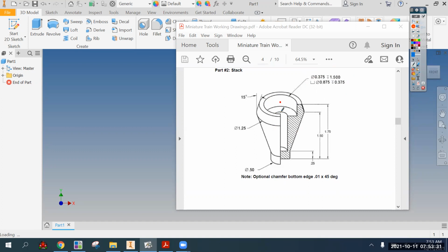So our sketch is just going to be a vertical line, the total height, a horizontal line, half of this dimension, because remember, when it gets revolved, it gets doubled in size. So we need to make that half. Then a little vertical line, a slanted line. That's a little tricky because we need to find this point, then another slanted line and connect over. And once we have this closed loop, we can revolve it and create the main block, and then two circle cut extrusions will do the rest.